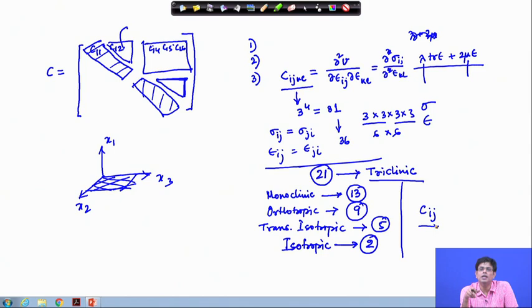This states that the Poisson's ratio cannot be arbitrarily large, and if one of them is large, the other one cannot be arbitrarily large. There is also a restriction relating the Poisson's ratios to the relative Young's moduli,